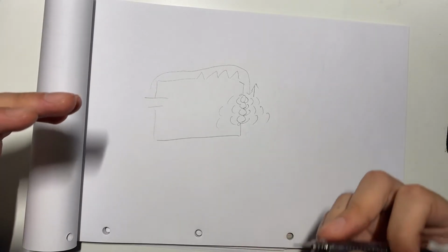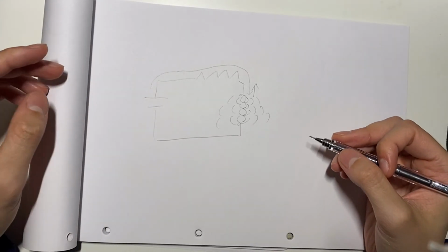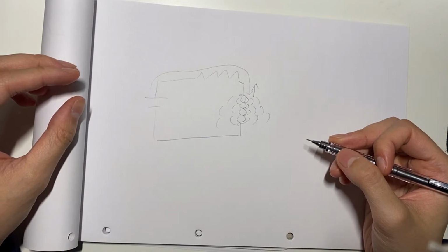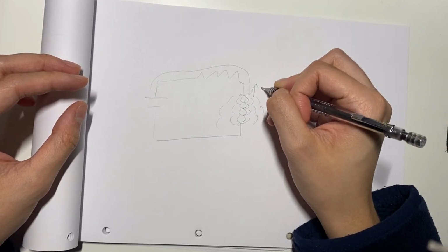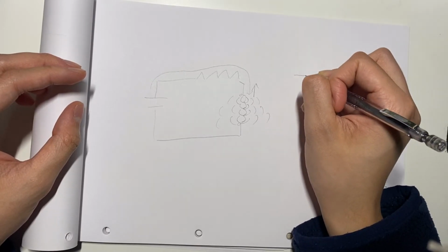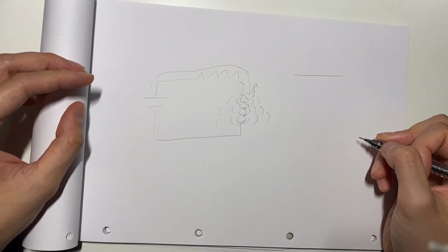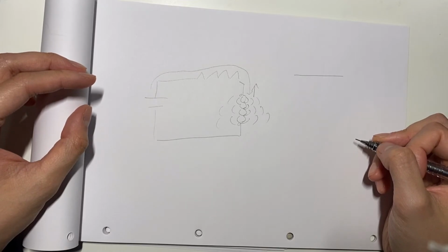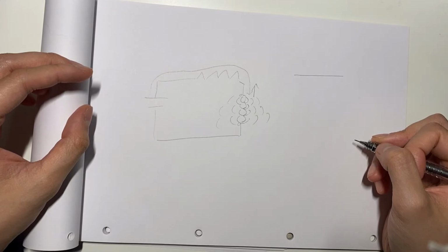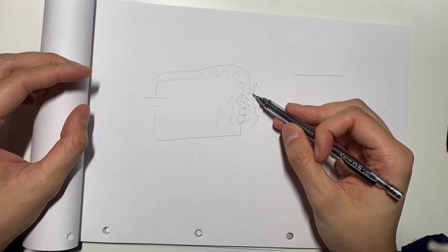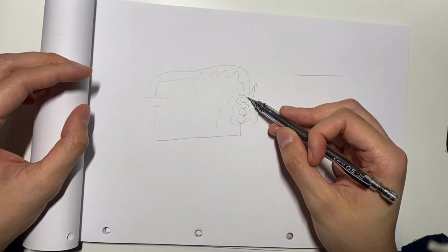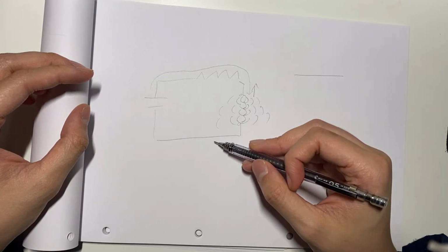This cycle repeats itself until we reach a point where the current has reached steady DC. And when this happens, the magnetic field no longer changes, and our inductor stops opposing the current. So this is no longer opposing, and it more or less just acts as a wire just flowing through.